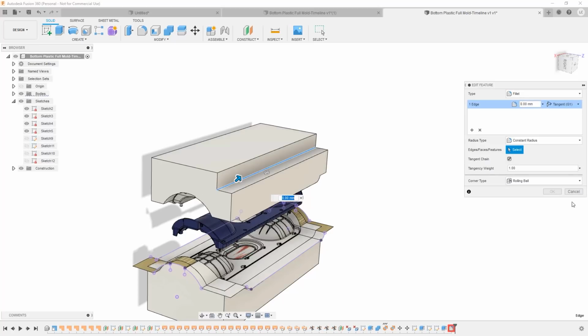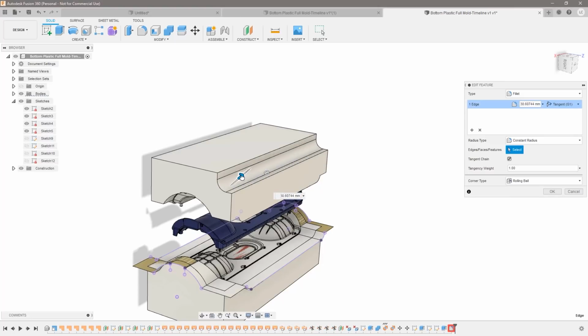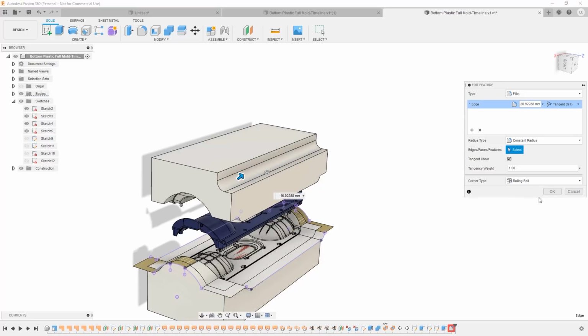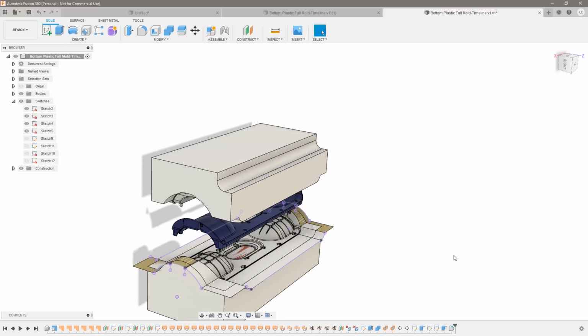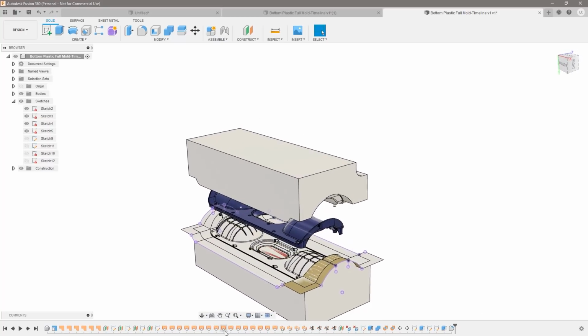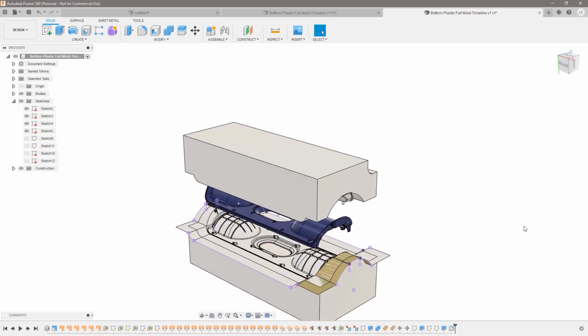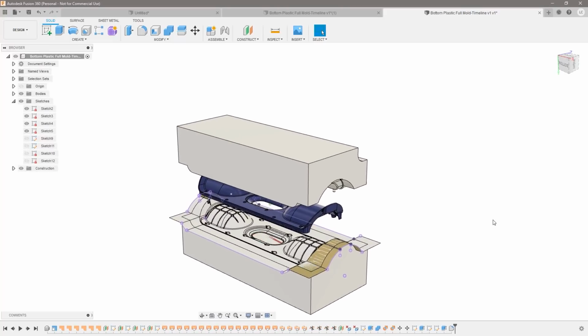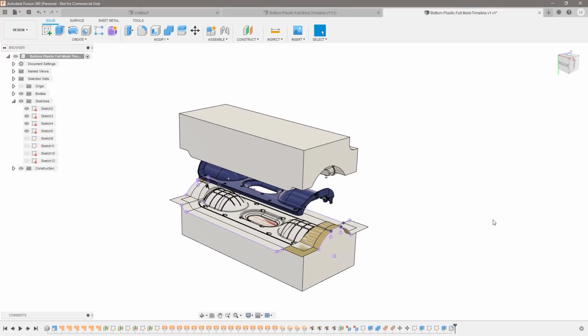So if we go ahead here and select this edge instead and give that some kind of a fillet, then the feature is now satisfied and is fixed. So as a professional, you definitely are not allowed to leave all kinds of yellow and red things down here. You need to solve these as you're working through them.